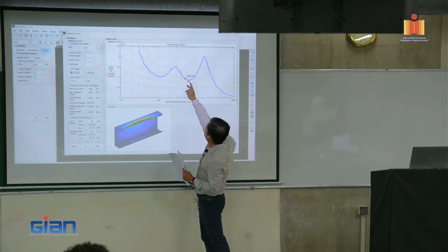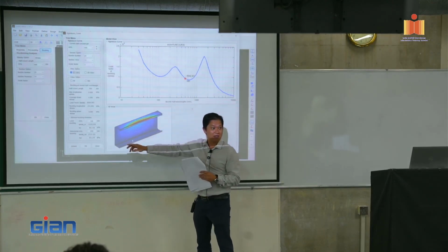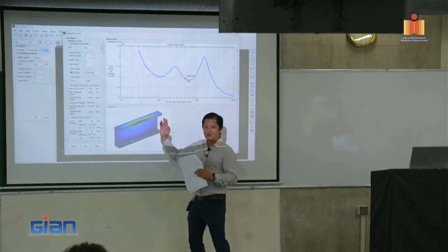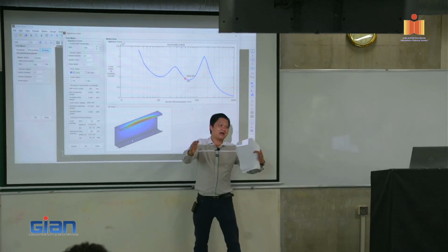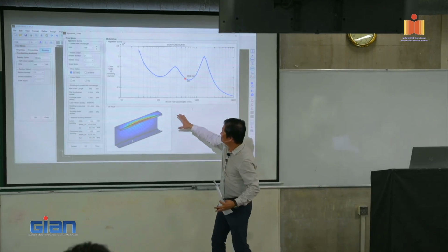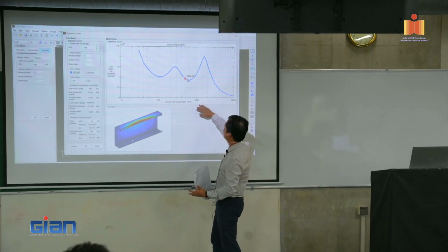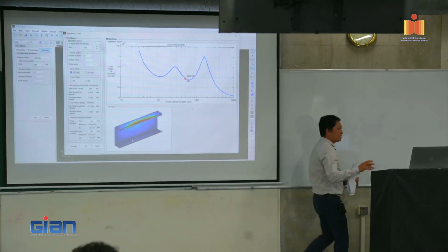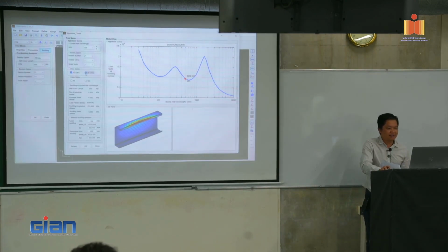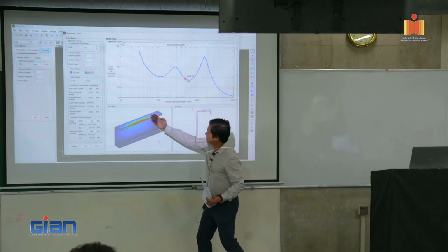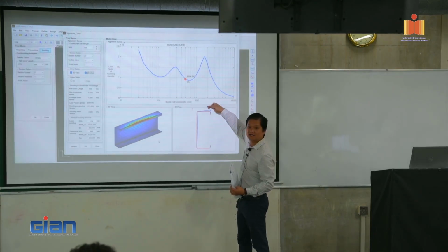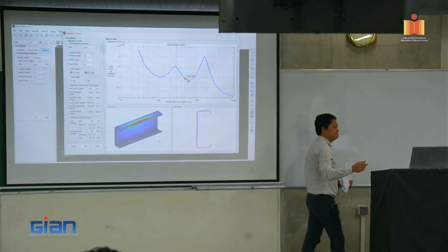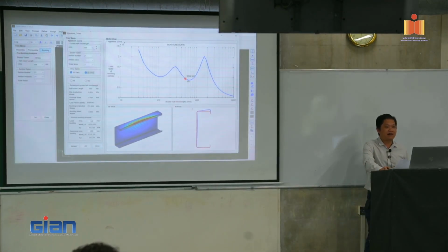And it's close to 500 here, it means that you see distortional buckling. So the lip is actually open, a little bit up. So remember, this is halfway. If I have 5 meters or something long, it's just another halfway, and just goes up and down for distortional buckling. That's how it works, halfway length. Okay, so you can actually click on 2D, it's a cross section in the middle. You can see that, this is up, right. So this is right in the middle here. So it's actually the distortional buckling. And this is where you choose 500 halfway.